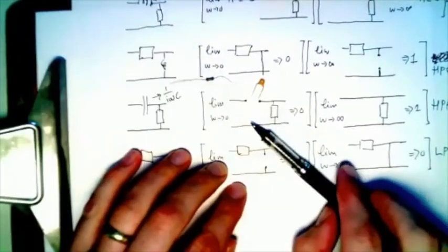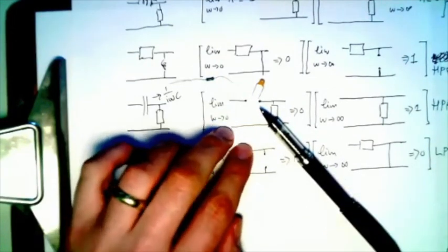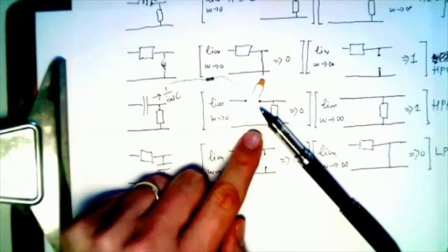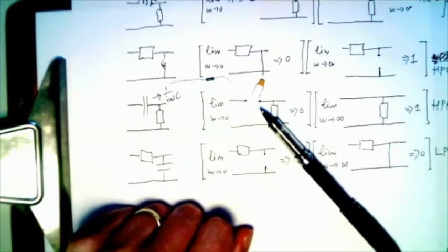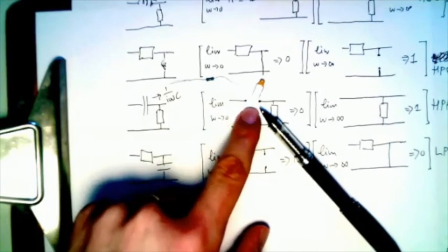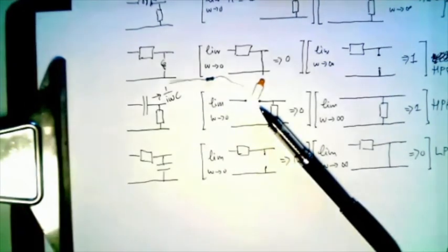So people cleverly figured out that if you query an old school analog telephone at high frequencies, you can actually listen in on conversations in the room. Just because at high frequencies, this thing doesn't appear as a switch that's open anymore. So there's a lesson in there somewhere: if you walk around and you pick up charge from one point to the other, and you discharge yourself, you are also changing your capacitance to the rest of the world. So you walking around just changes what circuits around you see.